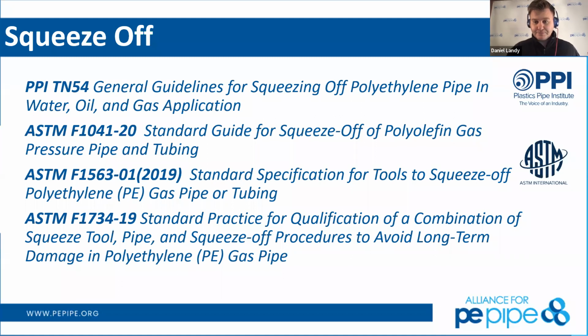That's my 2 cents. Okay, just to add to the question of if you overpressurize. First and foremost, if you overpressurize the pipe, and let's say it doesn't fail, but it does expand past yield, and you do have some deformation of the pipe. And I've experienced this in the gas industry a couple of times where they tested pneumatically, where they didn't take into account the compression of the air, and they did overpressurize the pipe, but it failed.